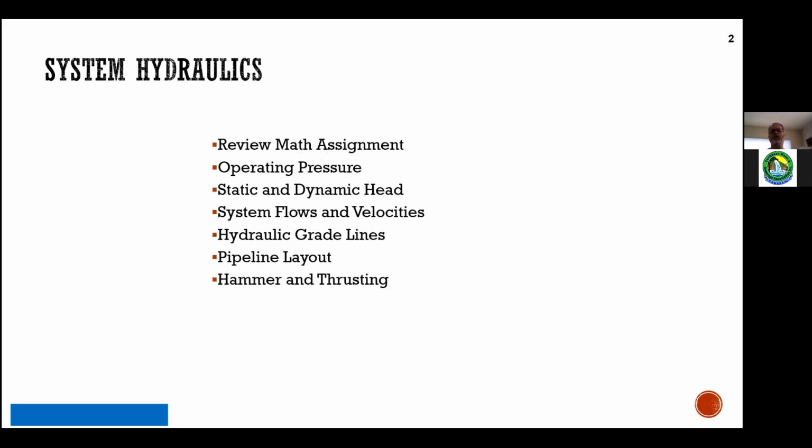So that when you're out working in your distribution system and you read a pressure gauge and you see a number, so many kPa, you'll actually be able, and this is what I've always told operators here, is I want you to try and visualize how high that column of water is above your head. Because when you look around your surroundings, and if you think, okay, I've got 20 or 30 meters of head above the fire hydrant or above my pressure gauge, I can actually visualize how much energy is available in the system with or without the aid of pumps or reservoirs. And it could be all three, reservoirs, gravity, or pumps, but how the system works.